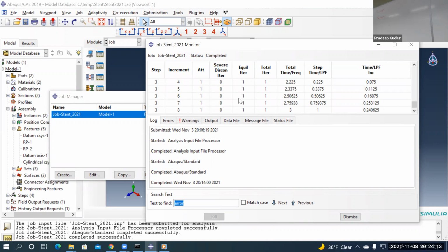Somebody, I mean, around the mesh, right? Yeah, only the running. Okay, so if you get an error, place it in a zip folder. It will reduce the size drastically. So right click on that ODB file and say send to compressed zip folder.